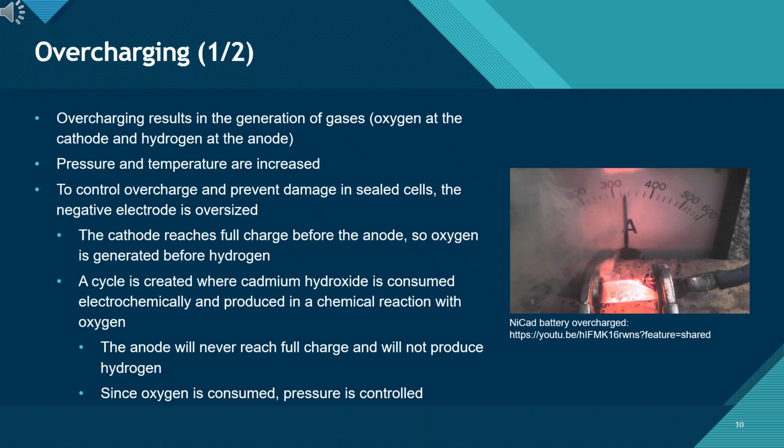In simpler terms, the cell is designed so that only oxygen builds up first, and that oxygen gets recycled back into the chemistry. This is why sealed NiCd cells can handle some overcharging without exploding.